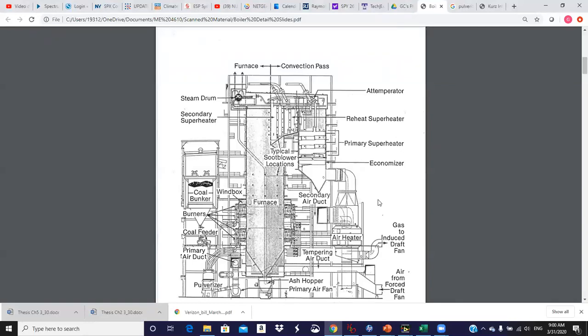So at the exit of the last feed water heater, we're still pretty hot. I can't remember the number on Kingston, but it's probably 350, something like that, Fahrenheit, roughly, give or take a little bit. And we're going to come over here to the economizer, which you'll see on the left-hand side. And that is, excluding the air heater, the last heat transfer section that the flue gases see before the air heater. And so that is just one more stage of feed water heating.